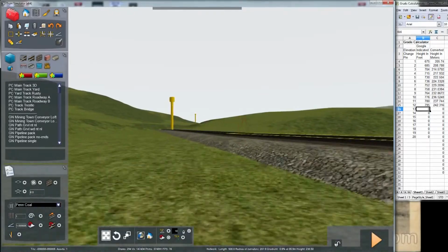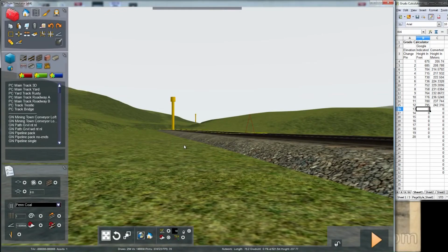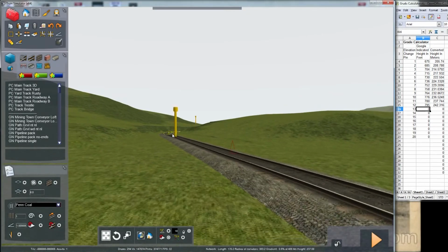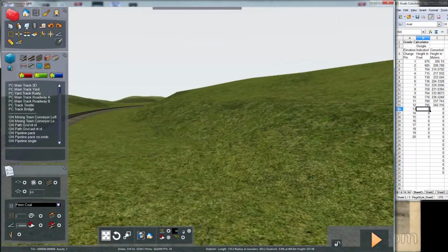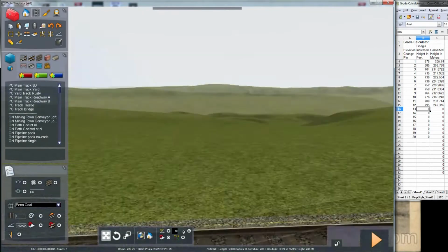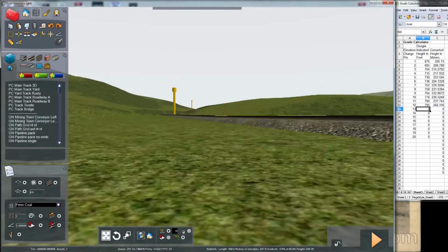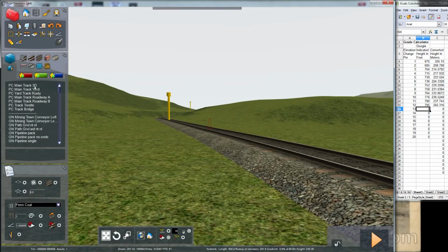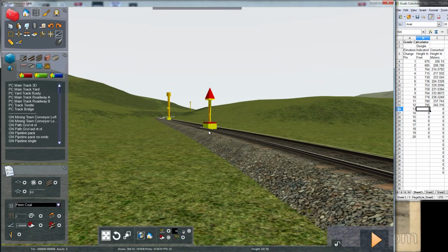So we've come here. Here's one of those spots where we had a little, there's our actual grade setting there. So let's look at this. And that curve is 0.9. I think we need to come up. We got a little bit of an elbow right there. So let's adjust that. Let's set the gradient tool. We're at 237.80. Let's come up just a bump and just see what happens. I noted that so I could go back if I don't like the change that I make.